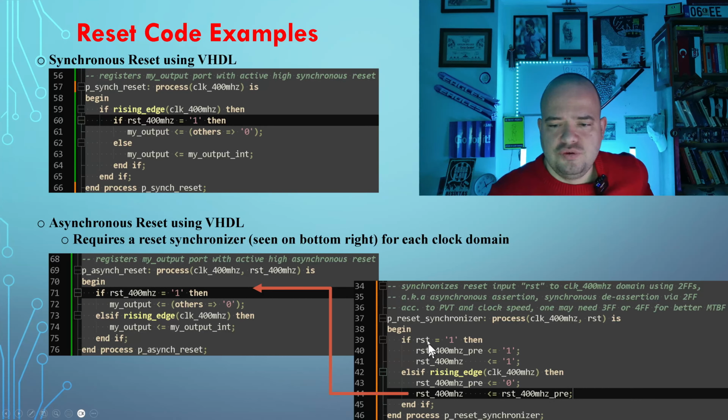But if you would have the same scenario like this, where the reset is only that RST signal incoming from your FPGA pins, then this is a reset synchronizer circuit, because it is different compared to a single bit, double, triple, or quadruple clock domain crossing solution.